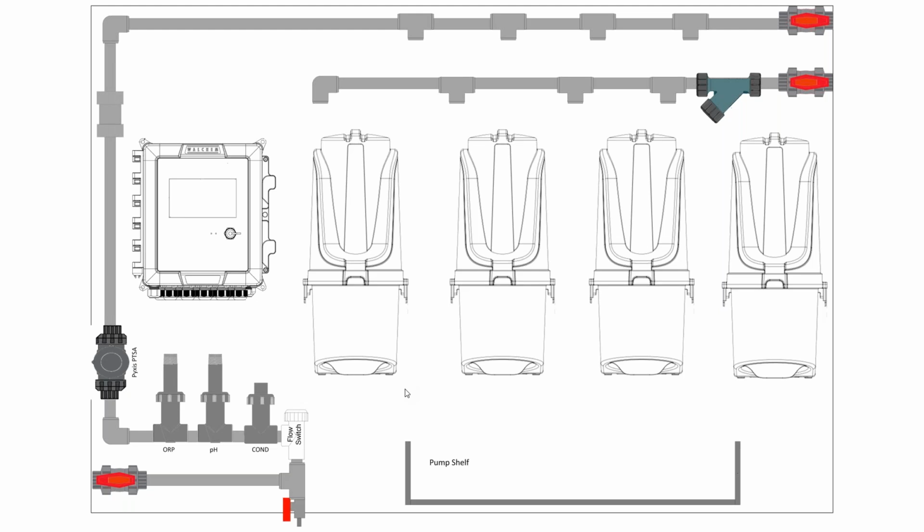Other people have done some cutoffs on the inlet. You can wire in a solenoid valve and maybe a little overflow indicator, so if you wanted to, you could integrate that into the controls package. It's just something to be mindful of if it did happen to stick open. With the UltraM design, it's less of an issue because it typically fails to close, but there is a potential for a little bit of that. So I would just take that into consideration on the install.